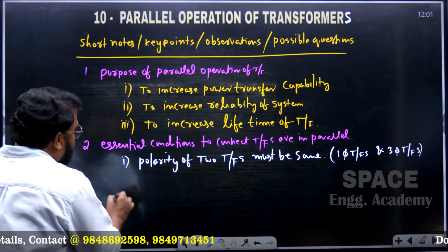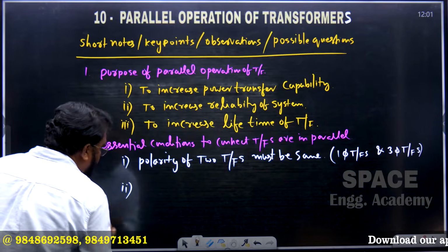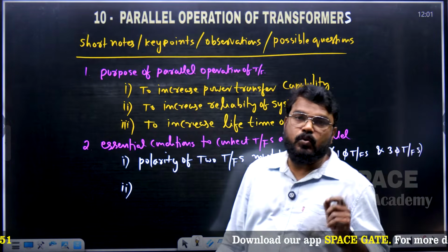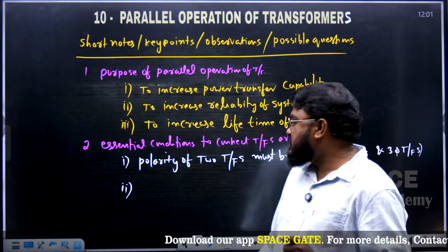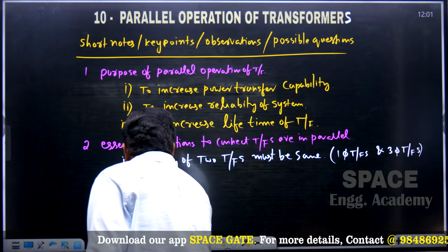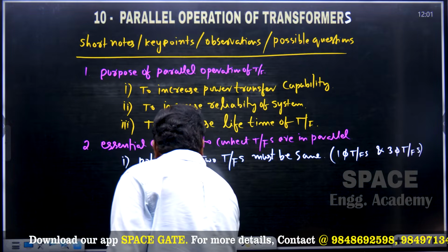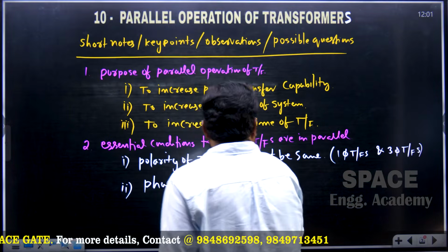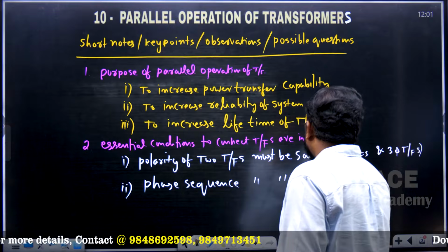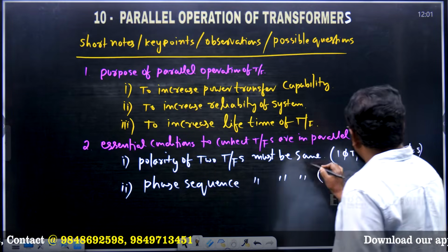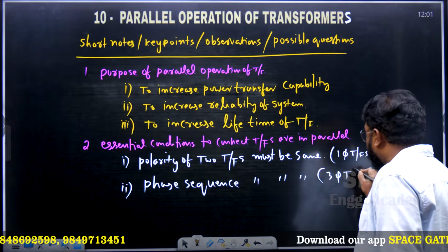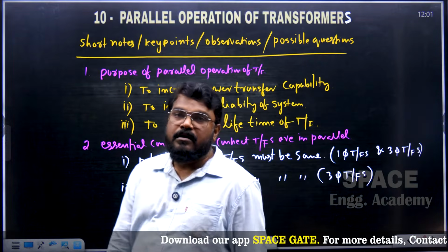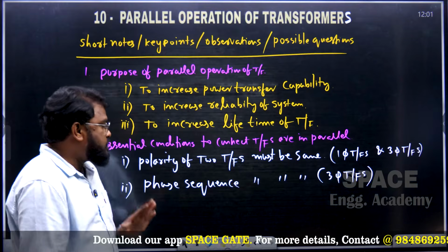And the second condition is that the phase sequence of the two transformers must be the same. This condition is valid for three phase transformers only.